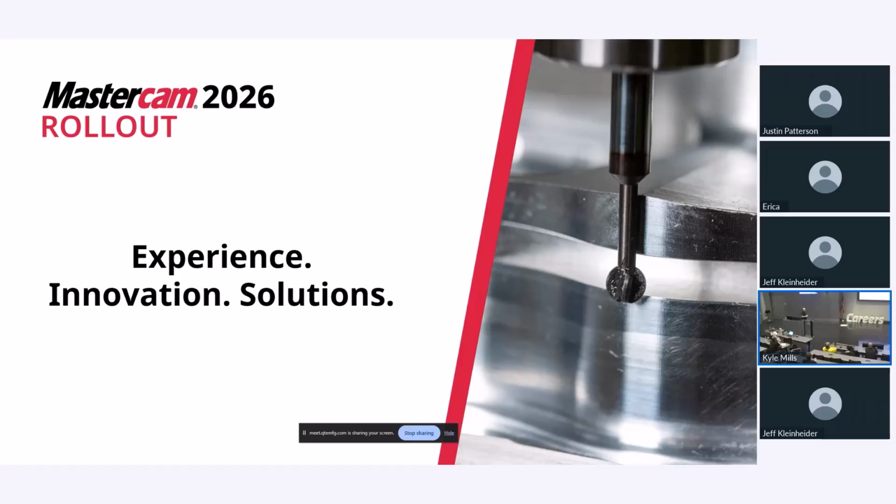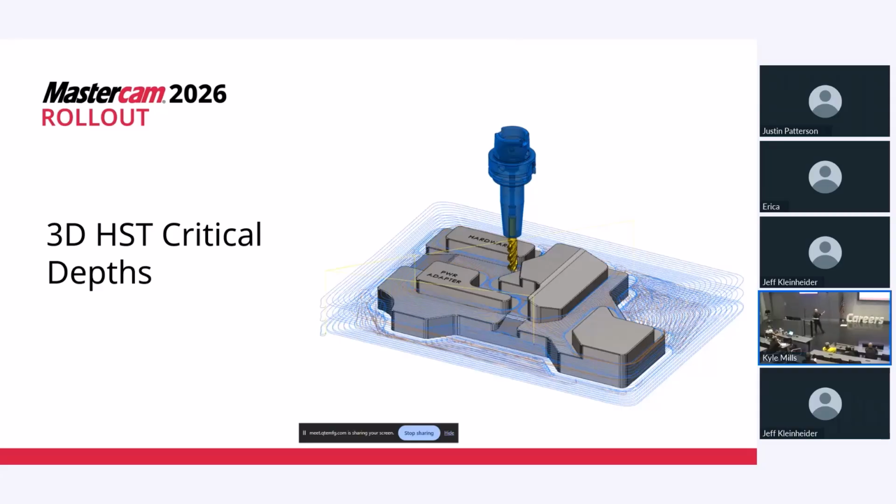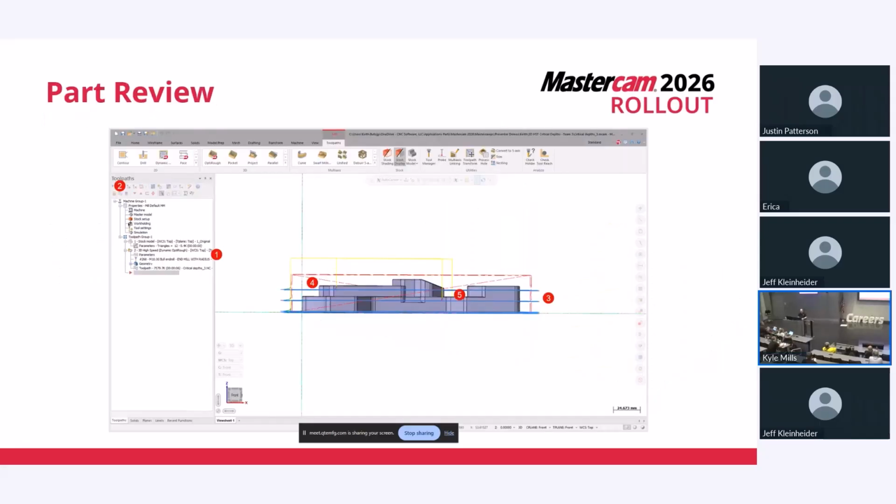To start, we're going to do something that I really like. For those of you familiar with the toolpath waterline, you know they have critical depths in there. We've now added that to OptiRough, which is excellent. You don't have to rely on step-ups anymore to go back and do all your floors. You can actually just click on those levels. I have a bunch of slides, but I'd rather just show you. So we're going to hop right in.